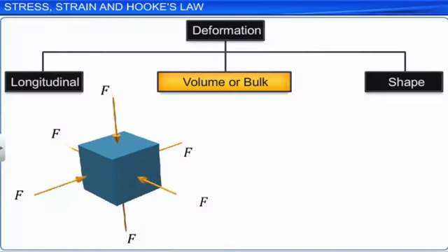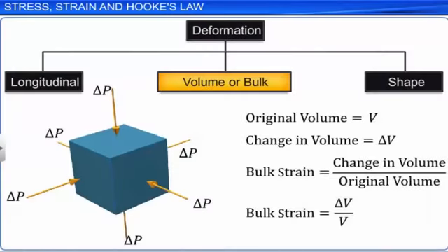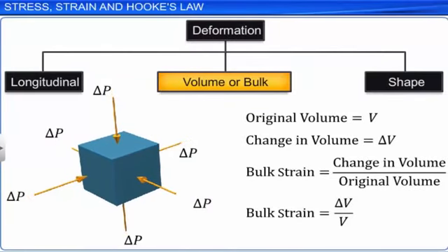If two equal and opposite forces act parallel to two opposite faces of a body, the shape of the body is distorted. When the deforming forces are a pair of equal and opposite forces applied tangentially to a pair of opposite end faces of a body, the shape of the body is distorted, and the stress generated is called tangential stress or shear stress. Shear stress is measured as the applied tangential force F divided by the area of the face A.